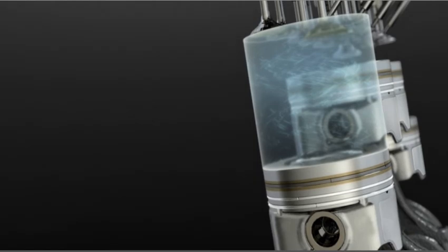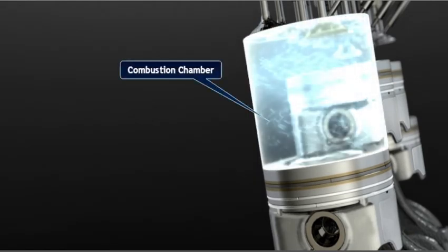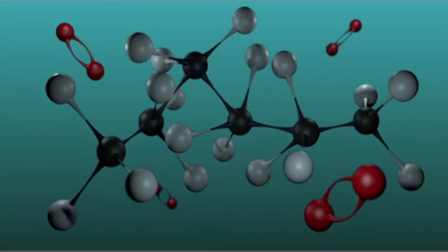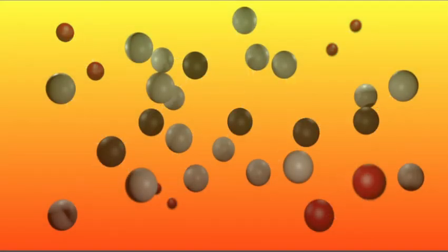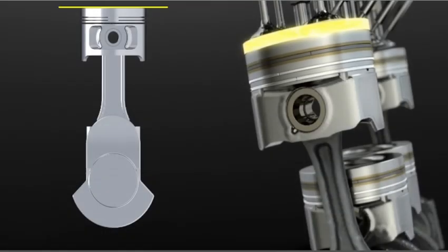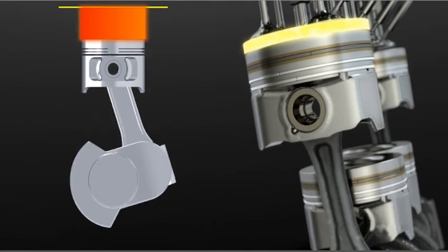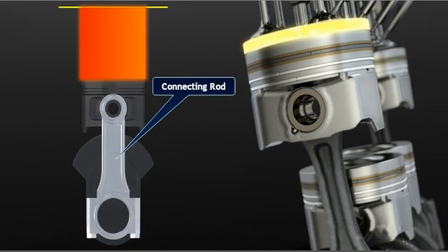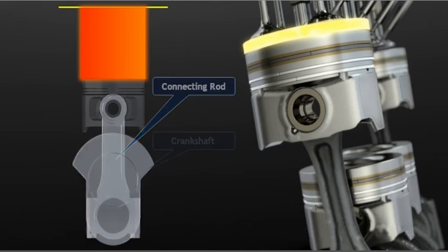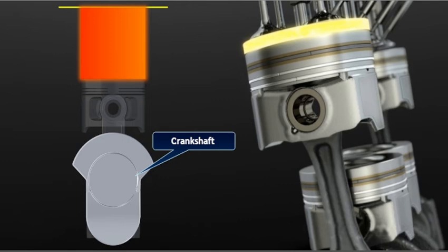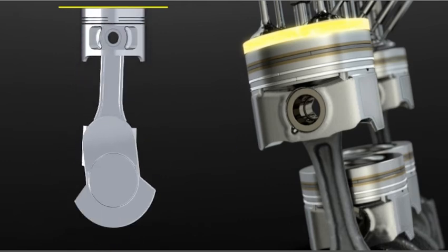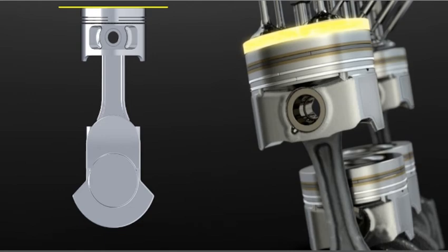Conventional engines manage a contained explosion in a closed chamber. The piston forms the floor of the chamber. Fuel contains tightly bonded hydrocarbon molecules. Combustion breaks the hydrocarbon bonds and releases the bonding energy. The released energy heats the cylinder's air and creates extreme pressures that push the piston down the cylinder. A connecting rod transfers the downward movement to the crankshaft, and the crankshaft translates the movement into a forceful rotary motion. The crankshaft's rotary motion is carried through shafts and gears to the drive wheels.